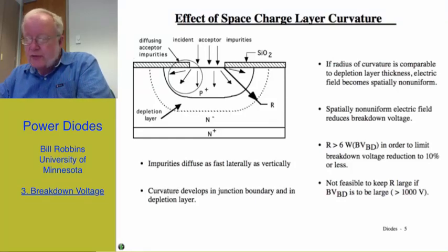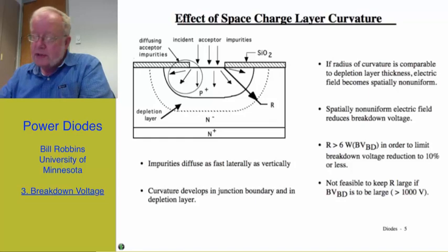The p-n junctions that we formed are normally formed by diffusion, and the result of the diffusion process, which I've highlighted here, results in the metallurgical boundary having a radius of curvature, particularly outside of the area where the window was opened in the masking of the diffusions in the process of fabricating the p-n junction. As a result, when we reverse bias this p-n junction, we have the same type of curvature in the depletion region. Here in the plane parallel section that I've outlined here,